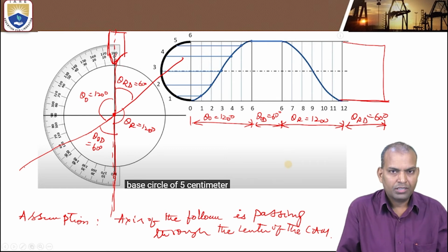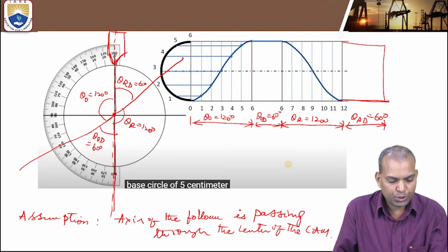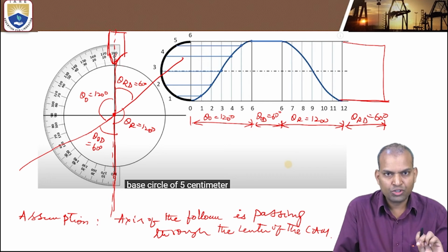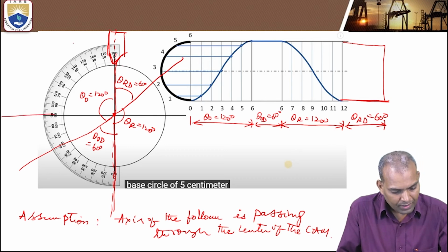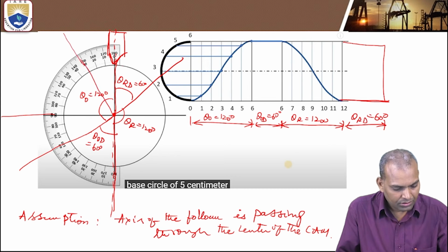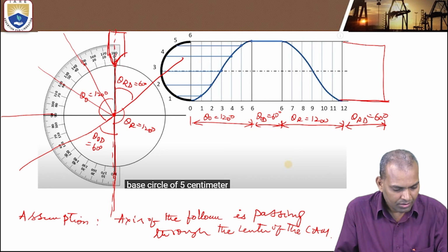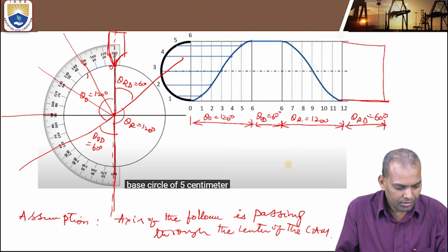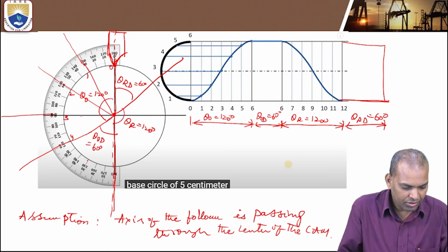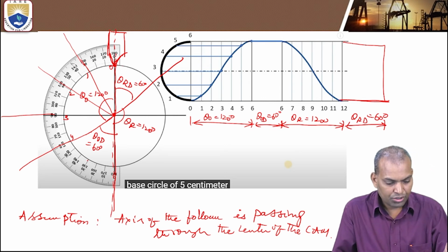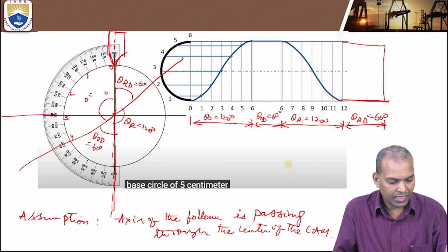Now after this, we divided the outward stroke into 6 parts. So divide this angle into 6 portions. What are the 6 portions? This is one portion. We divided into each 20 degrees. Okay, we have to divide this line into 20.